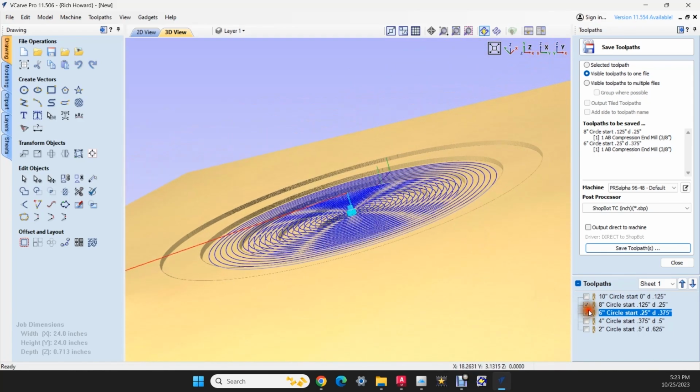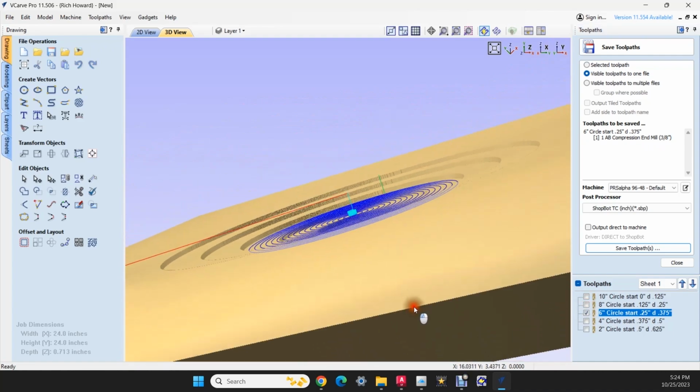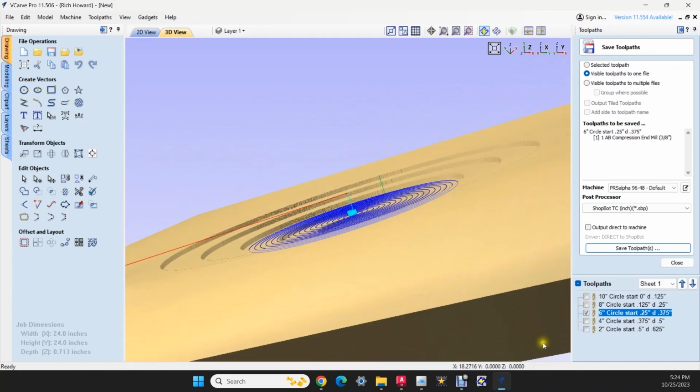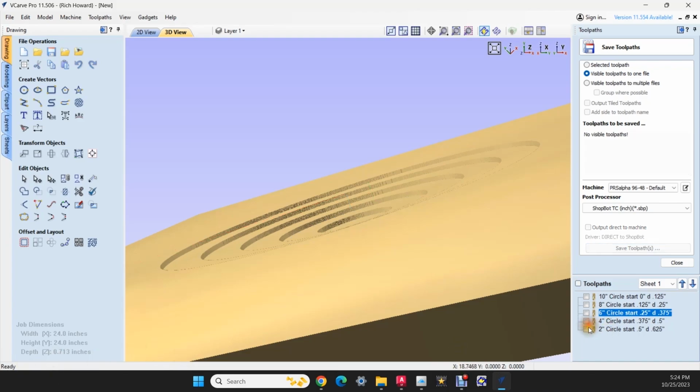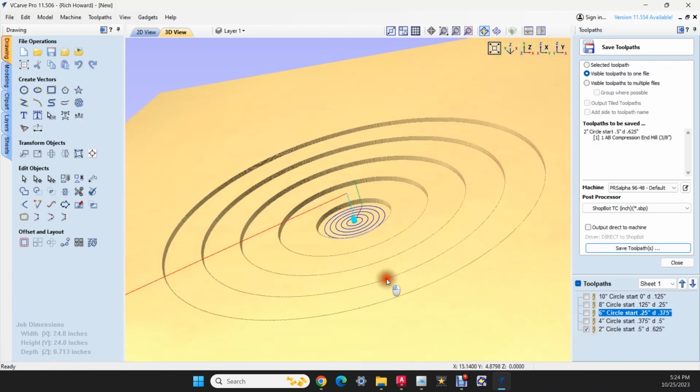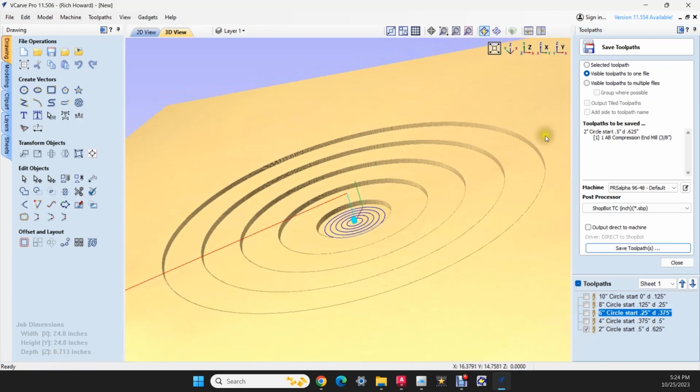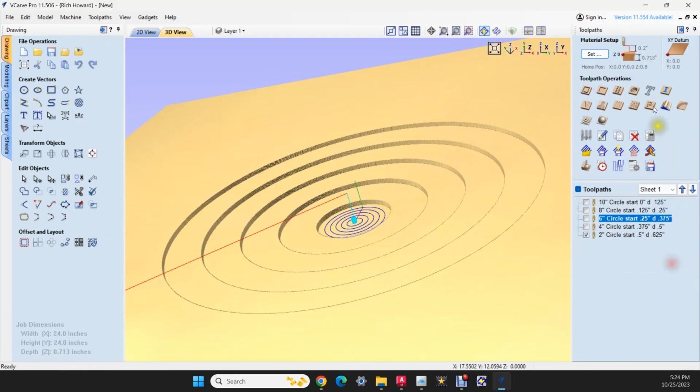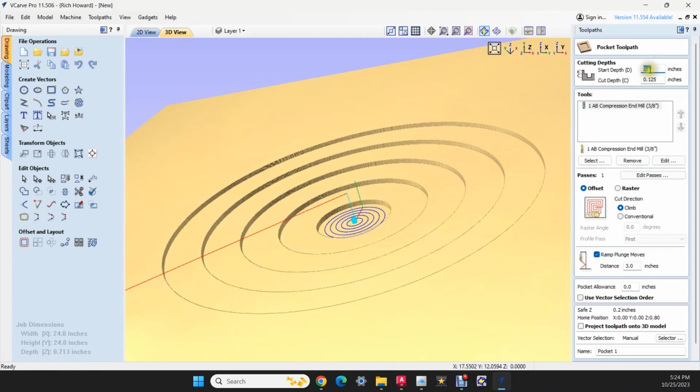Let's do the same thing. Bring in the 6-inch and pull away the 8-inch. Nothing is up in this level. And it's dawning on me, this is a great way to check the tool path as well, in the sense that I could create the same 10-inch tool path. I could give it a depth of 1/4-inch. I could tell it to run in 2 passes, and it's going to show those lines at 2 different depths. And there's our 2-inch diameter. And all of it is literally right here.